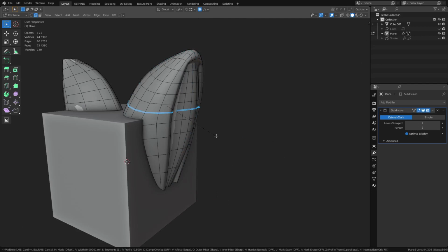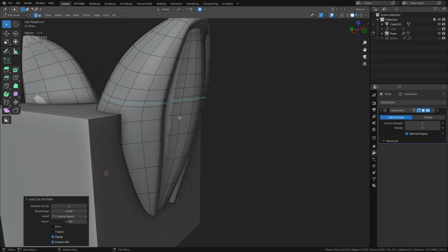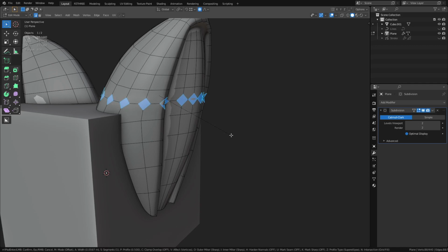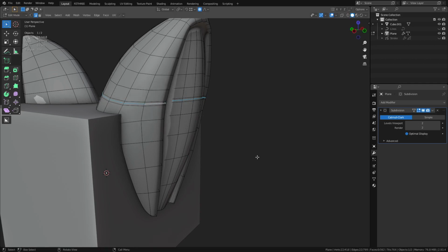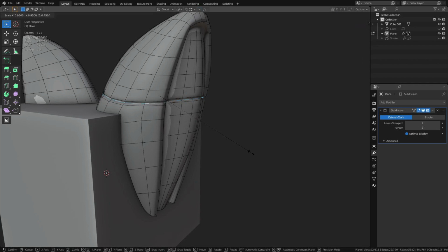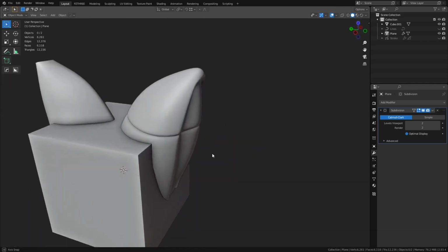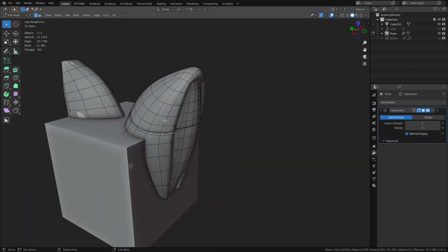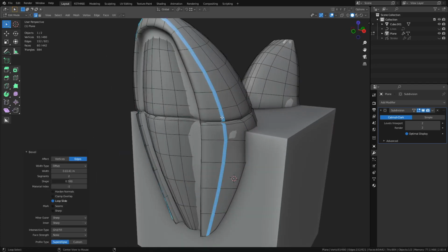And just a little side note, if you bevel an edge loop, insert edge loop inside of it, or give it when you do a bevel and hit mouse wheel up, you get that loop in the middle there. Scale that in, turn proportional edit off for this, scale that in a little bit, and start doing cuts like that in the models. So we might want to do that one there, and then also do one like that right here. Maybe something we want to do.